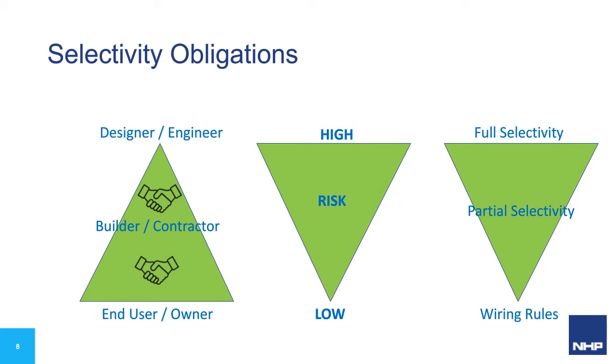We need to do one very important analysis, and this is an installation operational strategic risk analysis based on possible financial and data loss costs should there be an interruption to the supply. The interruption might mean anything from the loss of a distribution board feeder for 5 minutes to a full-blown main switchboard power loss for hours or possibly days.